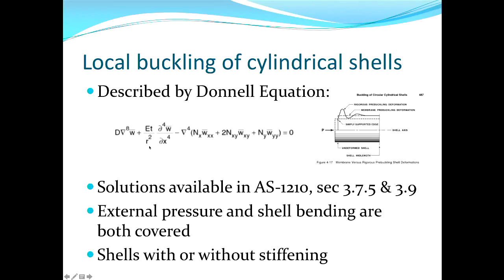But fortunately, we don't have to worry about any of that. The solutions to this problem are available because we're designing the prill tower to a national standard, the Australian standard AS 1210, and there's whole sections in that code that relate to local shell buckling. So we don't need to solve the mathematical problem, it's been done for us.